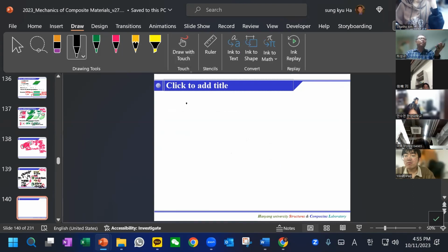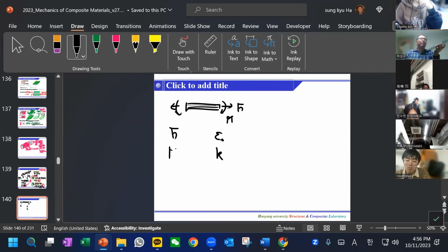Okay, so this is the A material. We have a force. We have a bending moment, and this can be many materials. Now, how much it extended and how much it curved is expressed by F and M equal EA times epsilon, and EI and K.